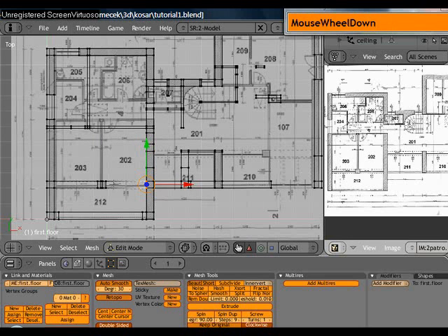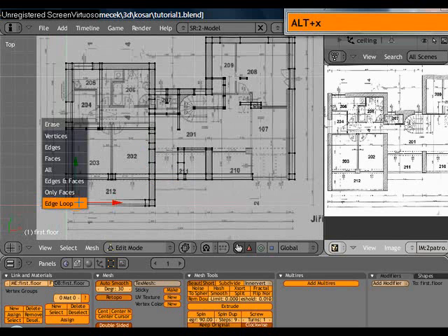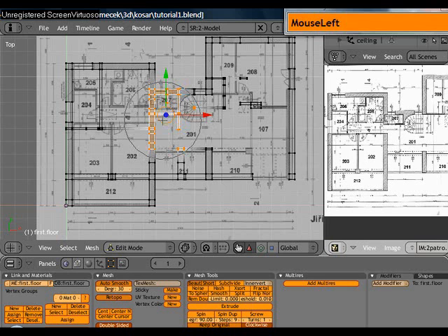And these were aligned, so I could do that. In here I'd like to delete that one. I'd like to delete all that geometry inside, so I will use A to deselect everything, and B again to use the brush select tool, and with my mouse scroll or my mouse wheel I can adjust the size of the brush, so I can now adjust what is going to be selected.